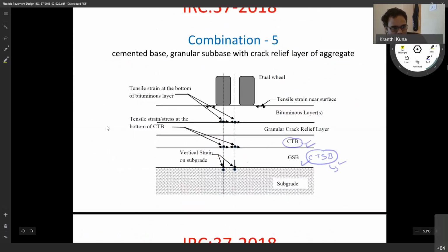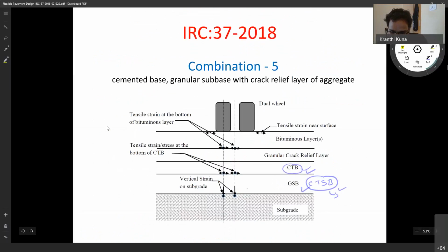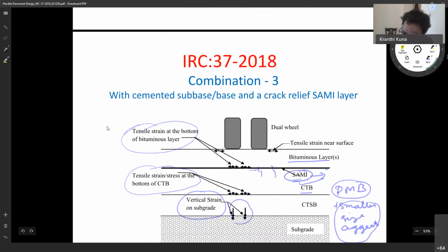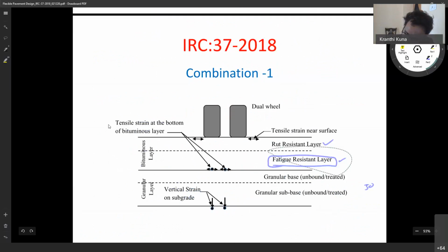See, I'll tell you what exactly it is. Maybe I'll use this one. So typical mix types, I'm just writing here. If you are having only one layer, I'm talking about a highway, you put bituminous concrete, SMA, and gap graded rubberized bituminous mix.